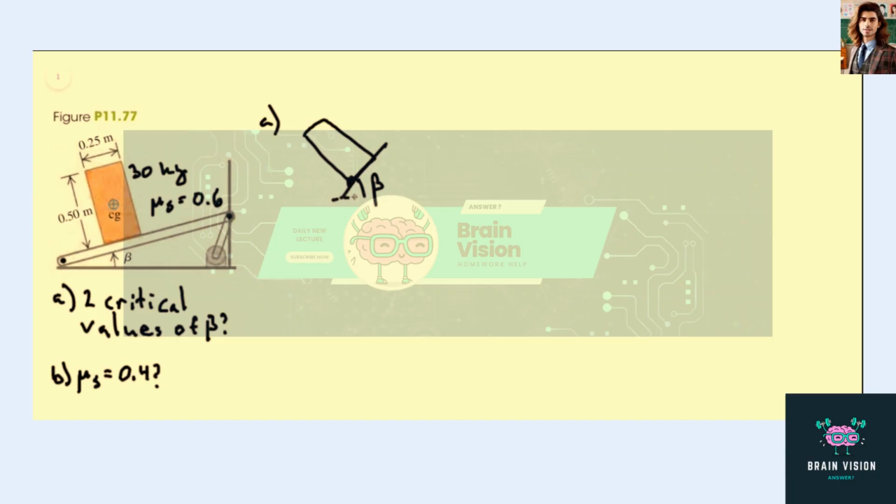And so if we look at the torques involved, then the torque from the normal force and from friction are zero because they're at our origin point. And so since the torques have to all add up to zero, then the torque from the center of mass also has to be zero, which means that it's pointing straight down through the point A. So this is not drawn to scale properly.